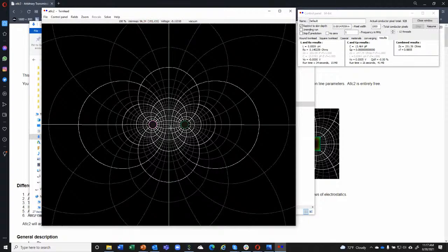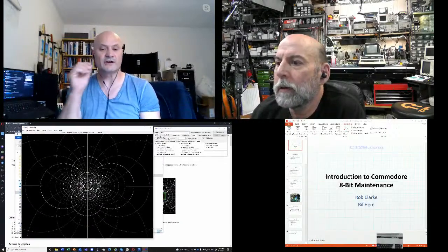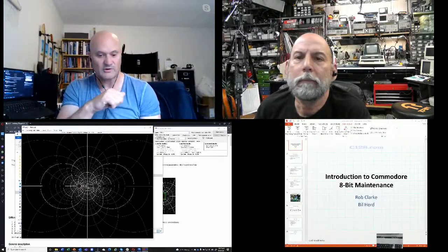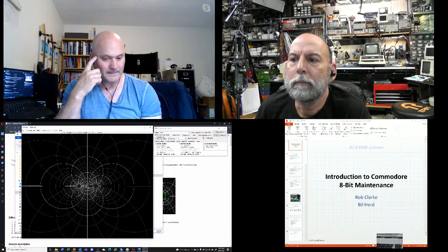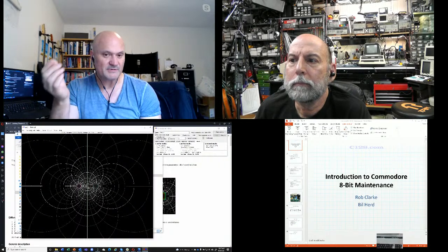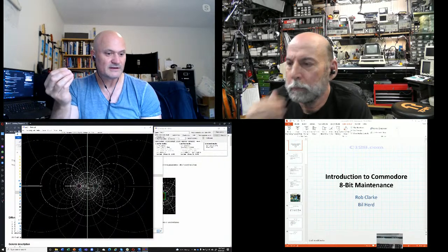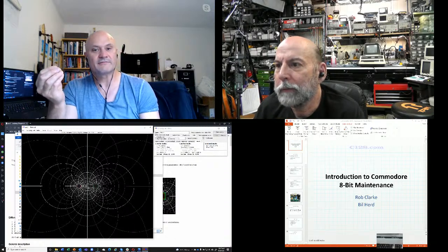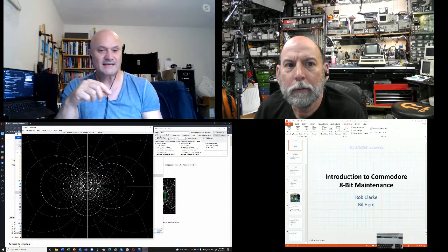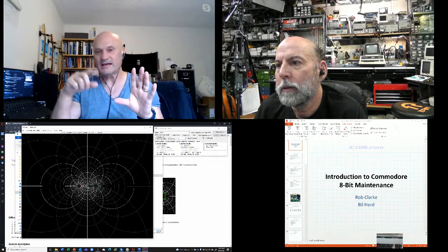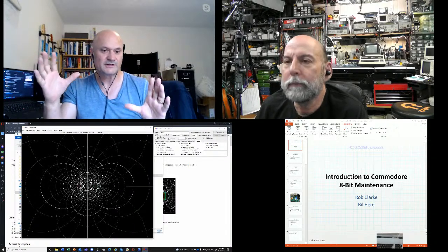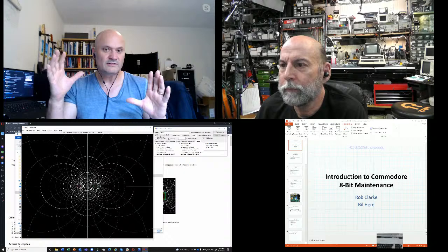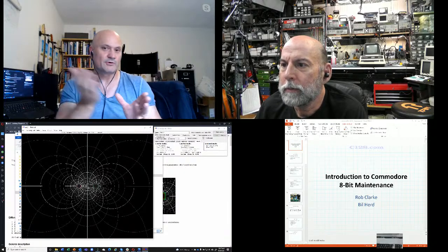Maybe that's unwanted. Or you'll notice if you're doing something with an ESP32 or similar RF microcontroller, the antenna that's the squiggly meandering inverted F antenna on the printed circuit board, that will never work if you put ground plane under it.